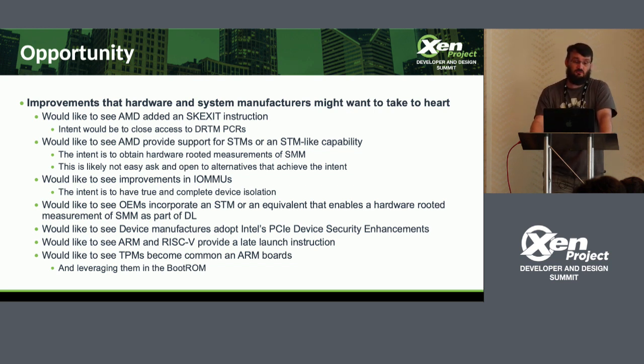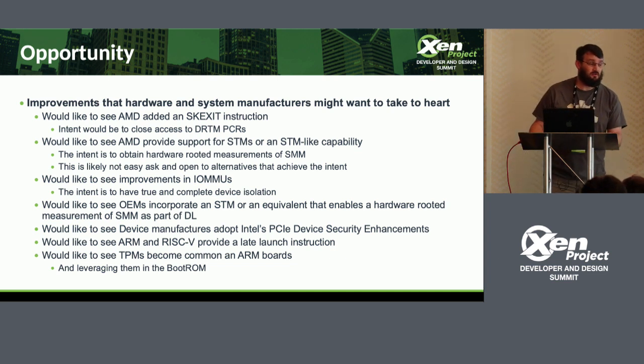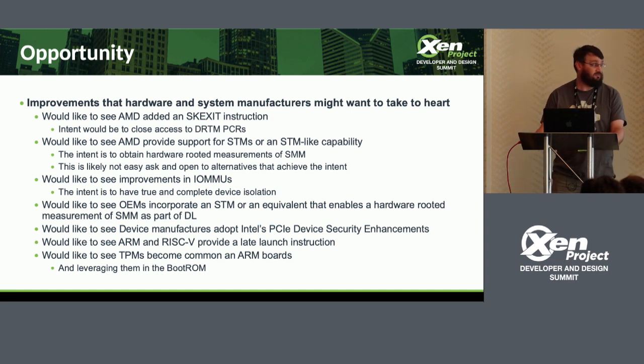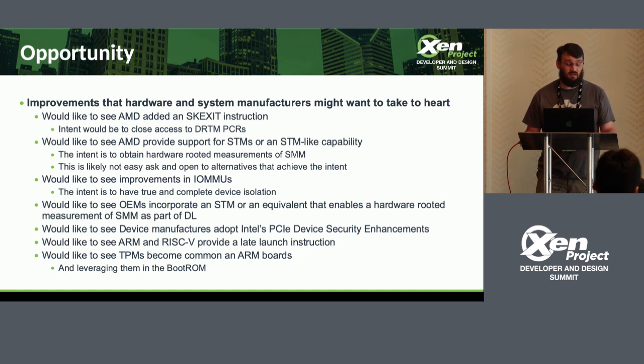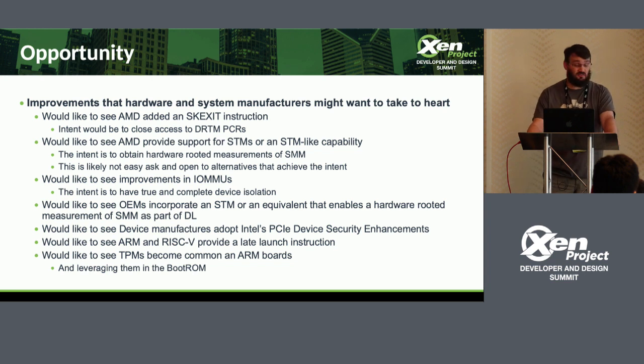That leads into device manufacturers adopting Intel's PCI device security enhancements. Right now we have no way of knowing what the firmware is on a PCI device. We can measure option ROMs, that's done in the SRTM, but for the actual firmware inside the device, we have no integrity. So Intel came up with security enhancements, a means by which PCI devices can do a lightweight launch integrity for their internal firmware, and provide that to the system to include in your measurements and attestation.